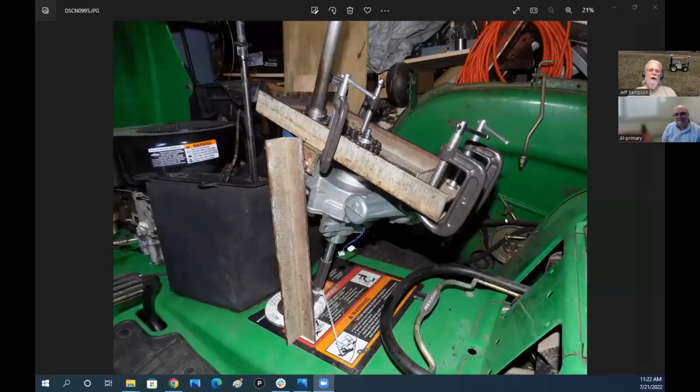Okay, so on this image here, let's see, my sharing looks like it. Okay, so here's my bracket up here that the motor's bolted on, and here's the steering shaft that goes up and down here. And this thing is a bearing that goes around the steering shaft, so this whole thing can swing back and forth because there's nothing to prevent it right now from doing that. So it turns out that this bearing is one of those pillow block bearings.